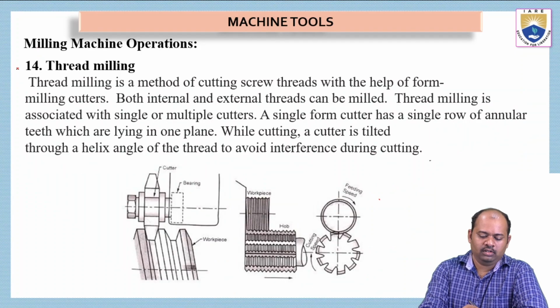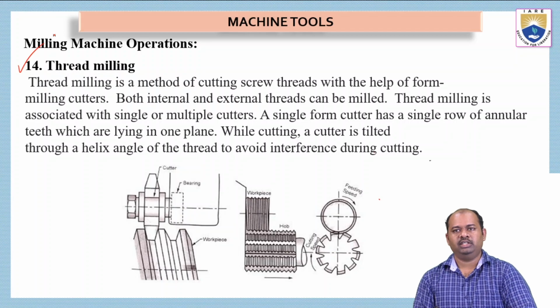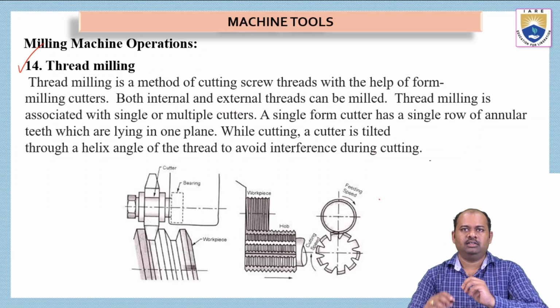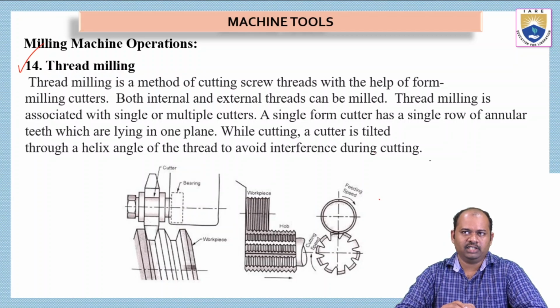And then we have thread milling. This is a process of cutting screw threads with the help of forming cutters. Both internal and external threads can be milled. Thread milling is associated with single or multiple cutters.